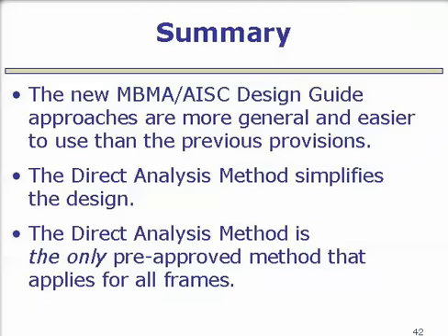All right, so to summarize, the new design guide, when it is here, is more general, and we think is going to be easier to program and easier to use than the previous provisions. The direct analysis provides definite advantages when you get into cases that are non-rectangular geometries, like gabled frames and so forth. So I think it's a very useful application of the direct analysis method here.